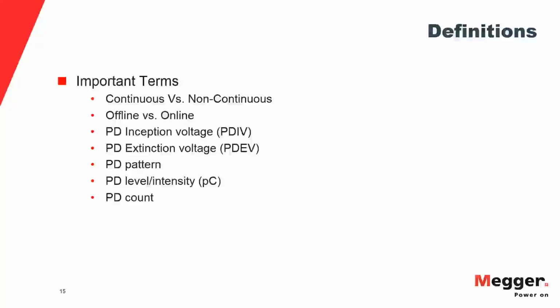We run the test for a period of time to create a map. After we find that, this can take anywhere from a few seconds to an hour. Cables in worse condition tend to be a little bit easier to map. And then we can end with a monitored withstand if we choose to, interpret the results and print the report.